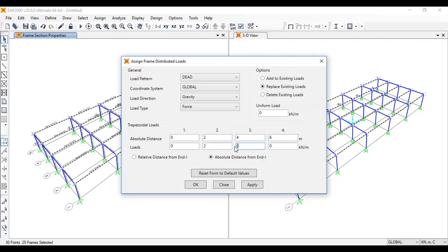Because what we are doing is we apply an imaginary unit load and get the resultant UDL, and then we apply that UDL to the beam. And then for the loads you actually have, you only need to multiply it by that value. That's it. I think this is going to be okay.